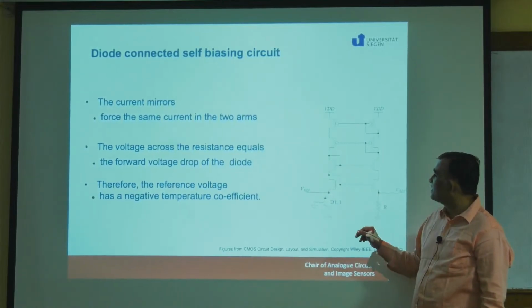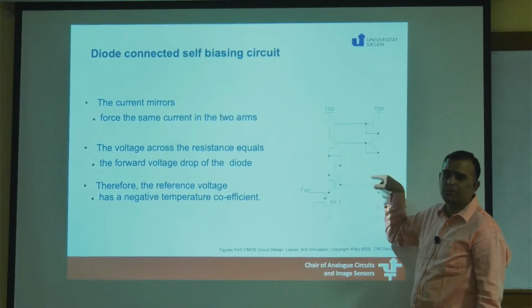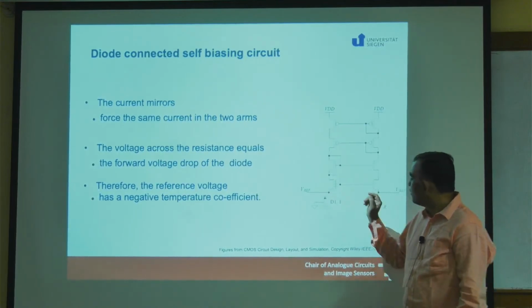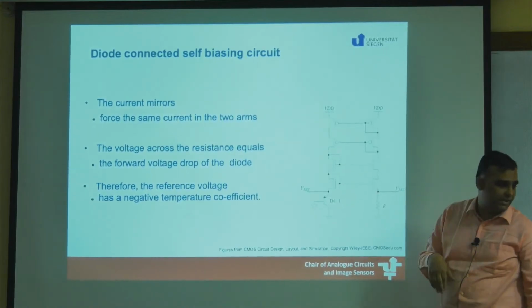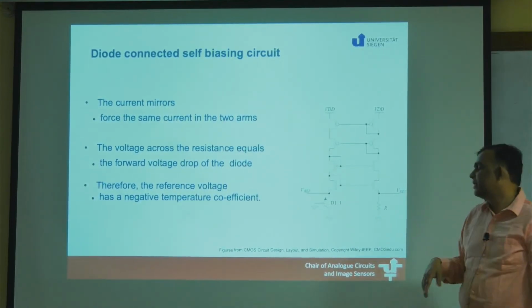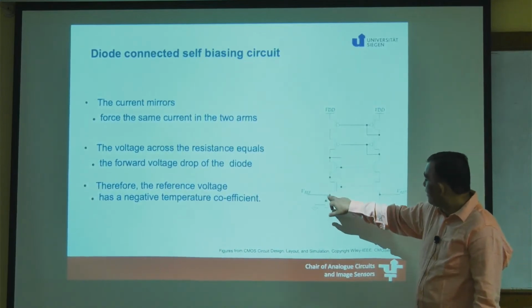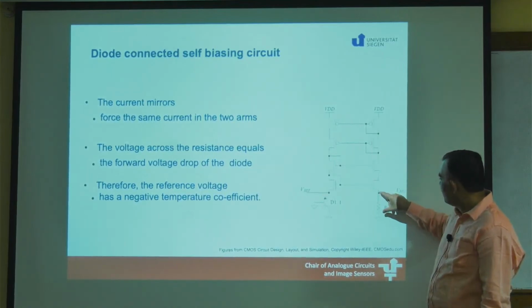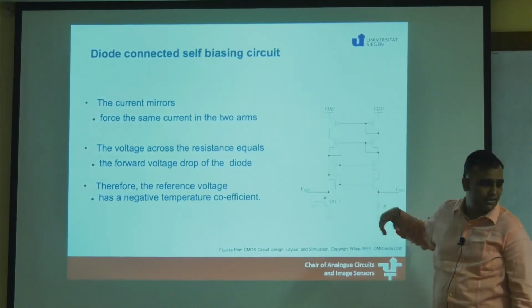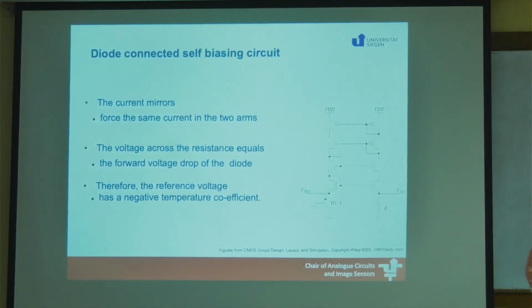Now this is a current mirror circuitry wherein we have got two NMOS current mirrors below that. This also means that this voltage should be the same as this voltage reference here, right? Oh, my apologies, my brain is dead. This will then change the currents which are flowing here, and we then allow a current to flow through a resistor. That will give me a voltage which has got a negative temperature coefficient, and the voltage as measured across the resistor will give me temperature sensing capabilities.